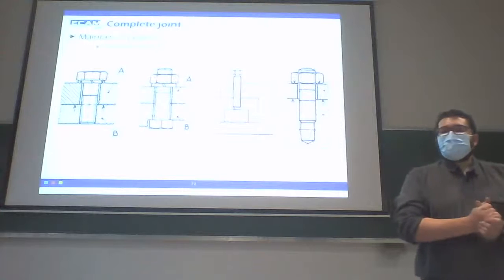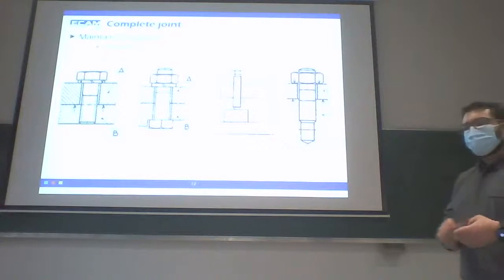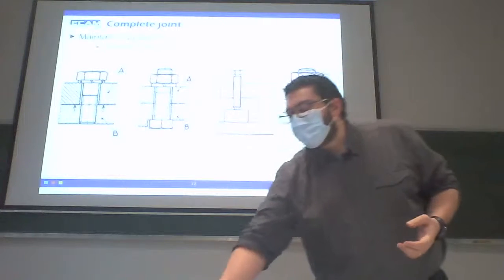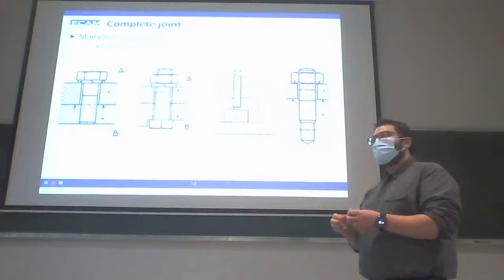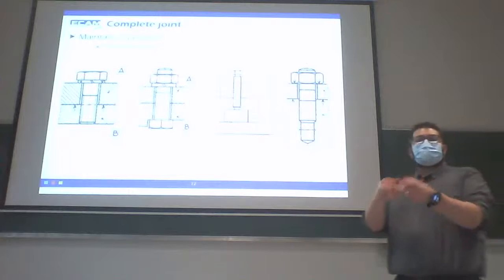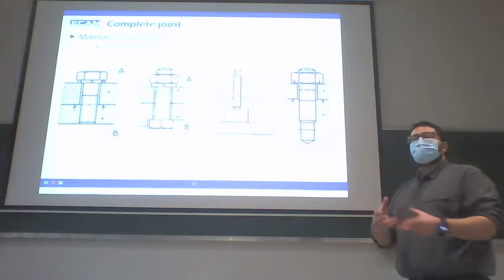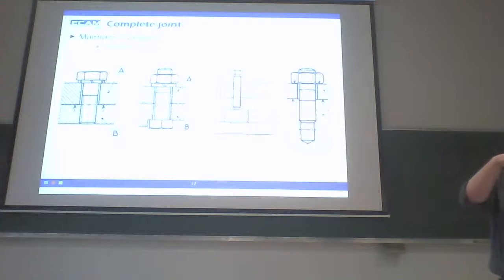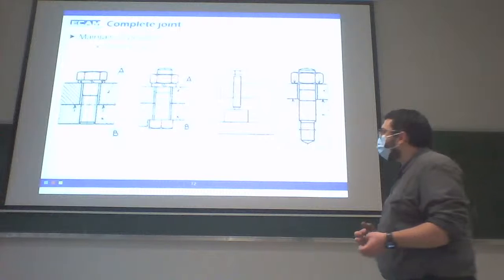Or last example, the use of a stud. A stud is almost like a screw, but without a head. We'll fix the stud inside the first part, in which we have the threaded hole. The second part is only drilled, and we use the nuts between them.